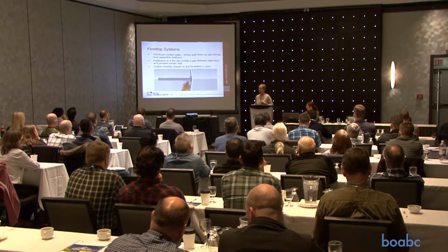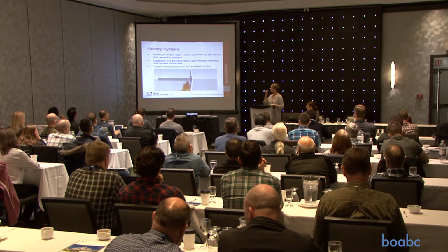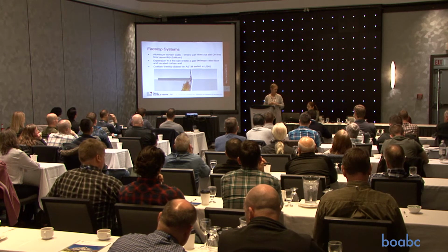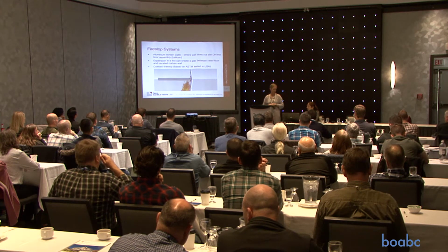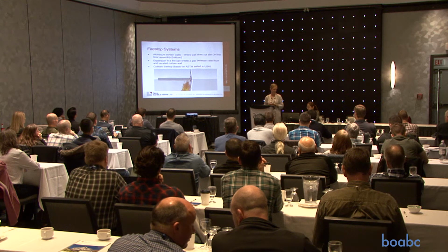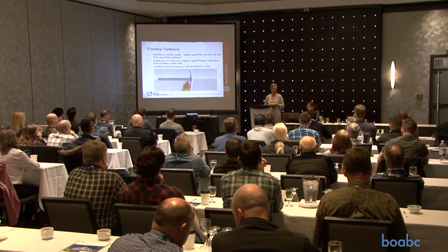fire stop. But yeah, we're always writing alternative solutions too to build some kind of gypsum board and mineral wool box around that piece to protect that. Like we would build a box around the bottom of that joint to protect the fire stop, because, well, in municipalities where they're on top of these things and they insist that we do. I think typically everybody else just uses the American fire stop.